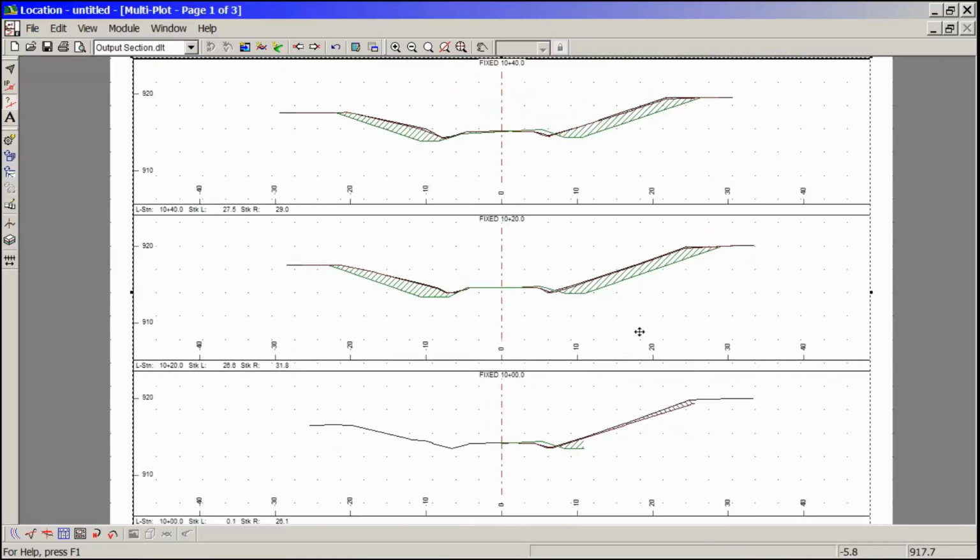Okay, so just a little recap of what I did from the start. I wanted to calculate the as-built volumes for a road. And what as-builts are, our surveyor will go out at each stage of the road and survey those parts of the road. First of all, the topo, and then it gets designed. And then he goes out and surveys the stripping. And then he surveys the final designed road.